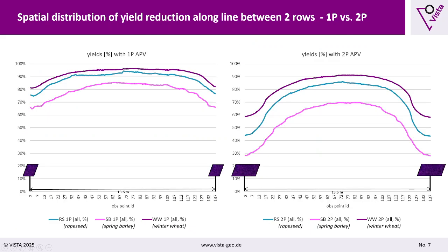The modeled APV configuration shown here consists of 50% 1 in portrait trackers, 1P, and 50% 2 in portrait trackers, 2P, both east-west tracked using backtracking to increase energy yields. In order to estimate the effects on crop yields in advance, simulations were conducted for winter wheat, spring barley, and rapeseed for the years 2007 to 2020. Simulations were carried out using downscaled meteorological ICON-EU data.